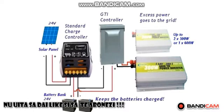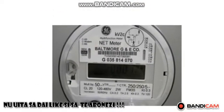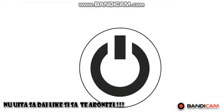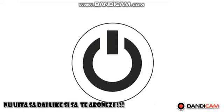The advantage of using a grid-tie inverter is that it can feed excess electricity to the grid and take advantage of net metering. Grid-tie inverters are more expensive because of this additional functionality. Grid-tie inverters can also be used without batteries. Some grid-tie inverters have the added functionality of shutting down the PV system in case of a power outage. This is done to prevent islanding, that is, grid-tie inverters ensure that in the event of a blackout, it will shut down to prevent the energy it transfers from harming any line workers who are sent to fix.